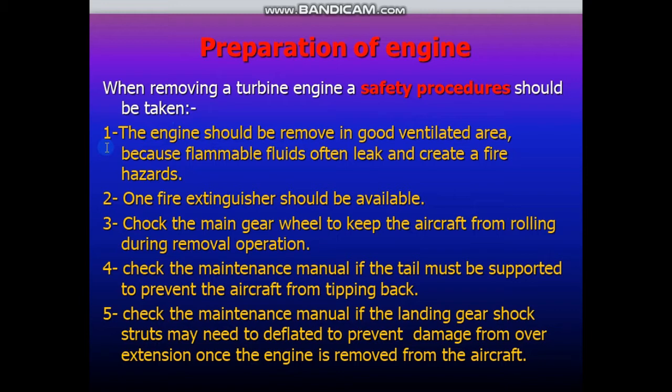The second safety procedure: one fire extinguisher should be available. Number 3, chock the main gear wheels. Why? To keep the aircraft from rolling during the removal operation.